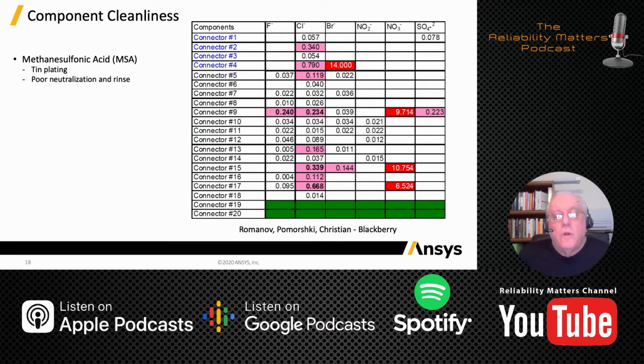What makes them benign is that third step of encapsulation. So what they showed conclusively is you need to process your boards so that you have a benign glassy state on the residue of those low solids or no clean fluxes. Those are good resources.